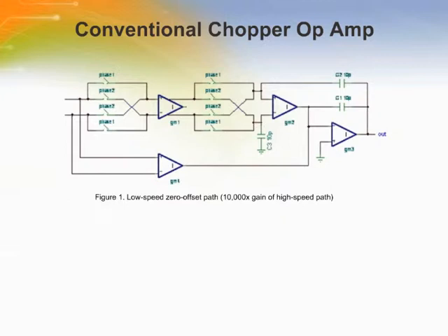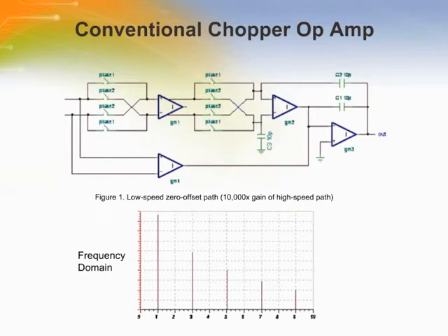An unavoidable artifact of the chopping process, however, is spurious noise produced by the chopper stabilization circuitry that is a correlated systematic noise harmonically related to the chopping frequency. Symmetric divide by 2 clocking creates only odd order harmonics, but these leftover odd order harmonic noises earn the modern chopper topology a reputation as being fundamentally noisy and limit its use in noise sensitive applications.